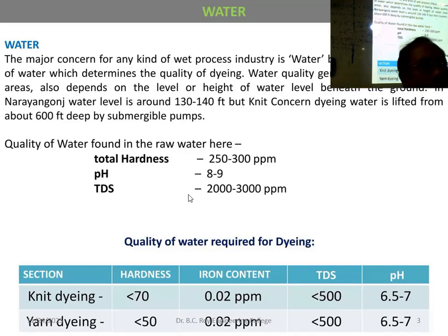Different types of salt, but they are not always hardness causing. So this is hardness and this is TDS. The difference is there. Hardness means calcium and magnesium ions; majority we are considering that. And here, total dissolved solid, all ions, whatever may be. NaCl is also there in the TDS. NaCl is considered in the TDS, but it is not considered in the hardness.